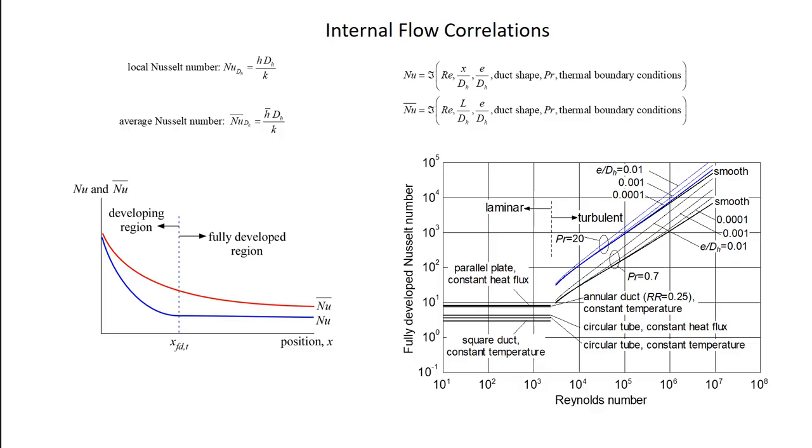All right, so let's do one last thing here, which is, again, let's look at what the correlations give us and do that with an eye towards remembering how these internal flows behave, right? Because once again, it's not that satisfying when you see something that your model is doing and you ask the question why, and your only answer is, well, that's what the correlation says it should do, right? I mean, you ought to be able to know why the correlation is behaving the way it is, okay? So what I did here is the same thing that I did previously for the friction factor, and that is I took the limit that L over D goes to infinity.